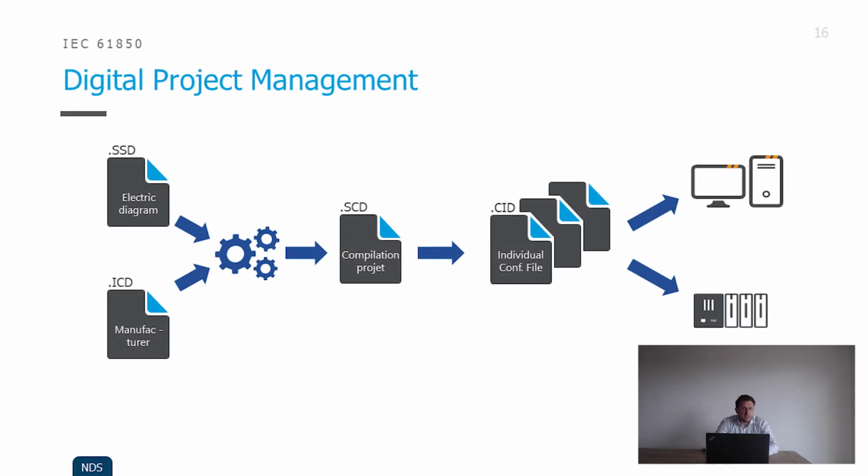But IEC 61850 is not only a protocol standard seen from a communication perspective. It also includes a system configuration descriptive language, abbreviated SCL, which you might have heard before. It is a language or representation format for configuration of electrical substation devices. So let's have a quick overview of the idea behind this language.